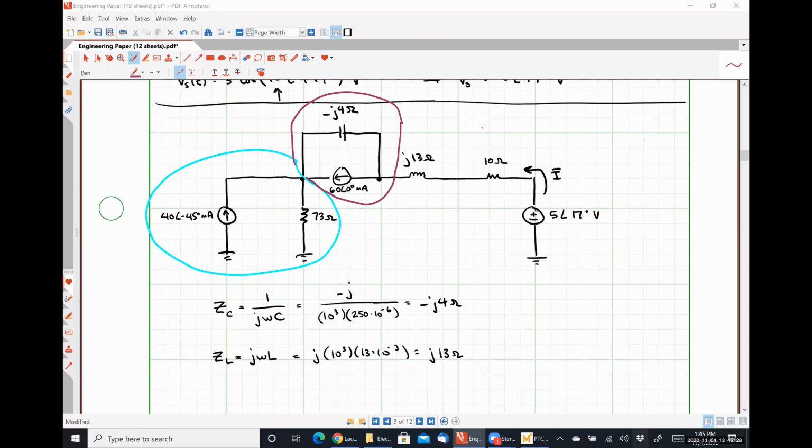So just thinking out loud here, with my voltage source on and both of these current sources off, I have a single loop circuit and I can figure out the current that's leaving that voltage source pretty easily, or the voltage source's contribution to that current pretty easily, right? If the 60 milliamp current source is on, then it's simple current division.